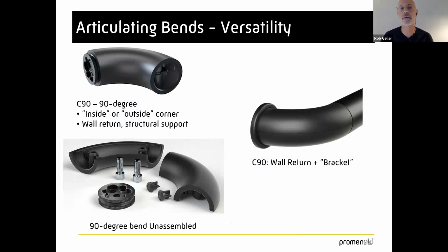So you can even come off at a 32 degree bend. And all you do is, it's just a hex screw. You just need a ball hex screwdriver. It's a standard size. You loosen it up, and this is 2 of them put together. I don't know if you can see. And if there's 3, you can just loosen this up, rotate the 2 outers, and you create the bend on the job site.